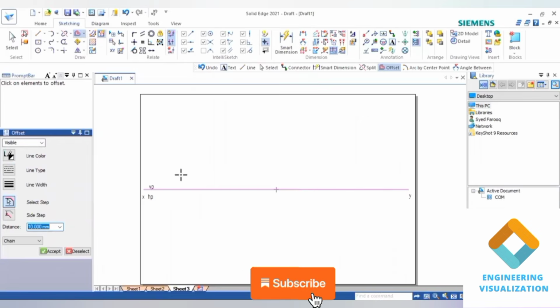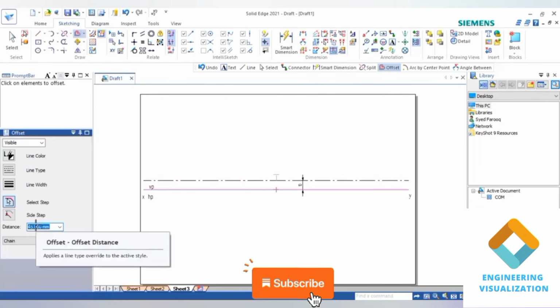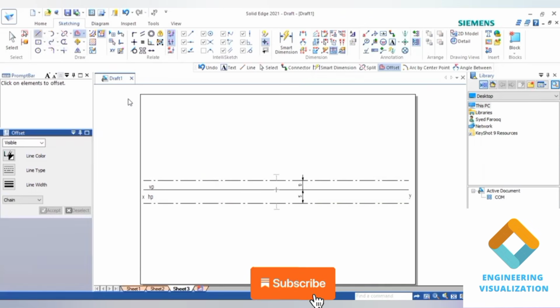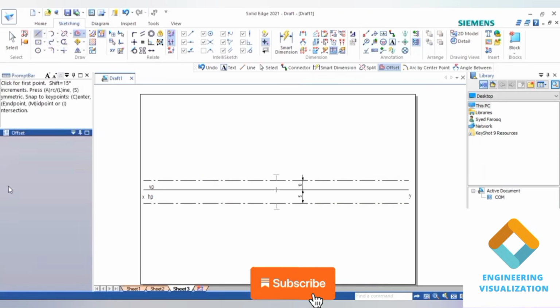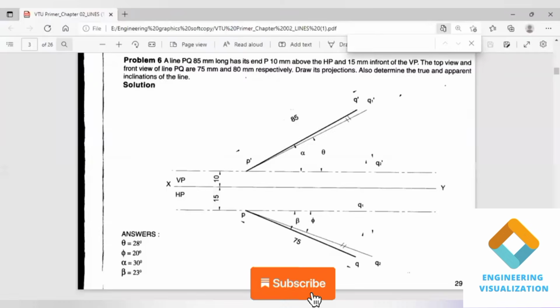I'll be using offset command. So select the XY line and give the dimension 10 mm. In the same way again you select XY, give the dimension here 15 mm. Okay, now we can see that the apparent length given here. So apparent length, okay, so this is we consider as a end points.